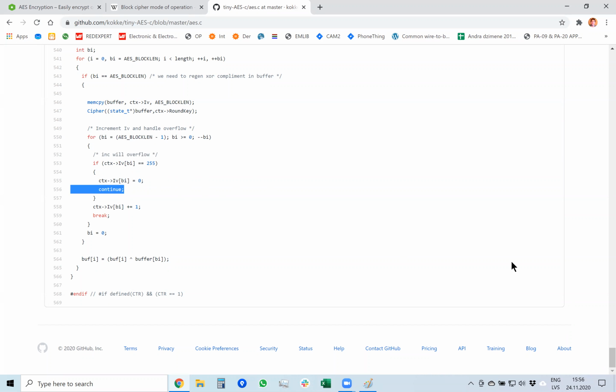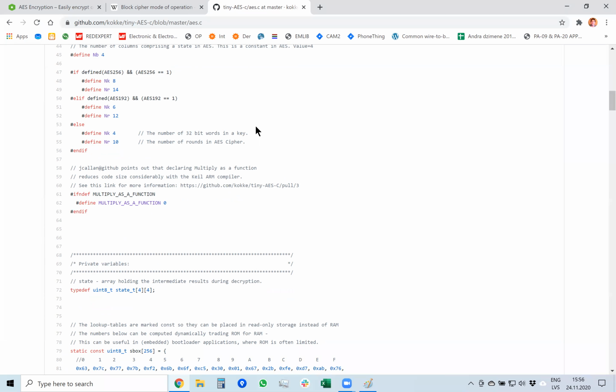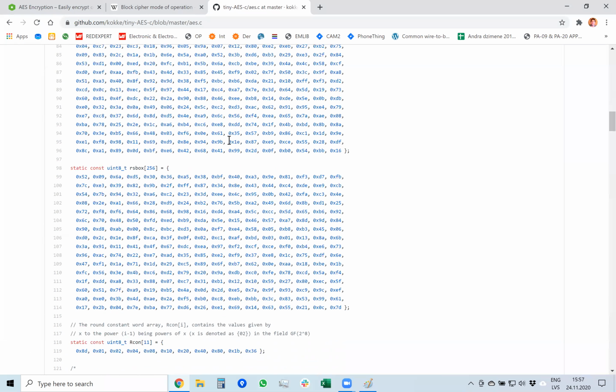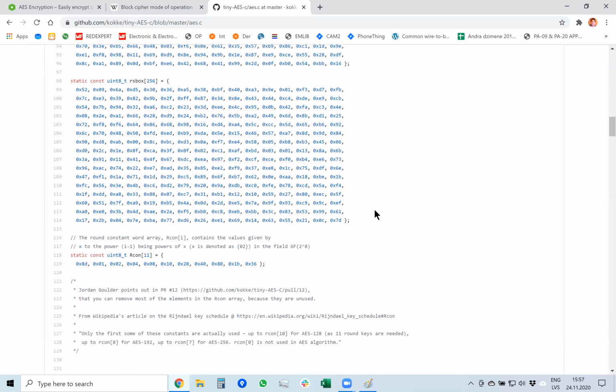But knowing that encryption is really important, people have started to build encryption, for example AES, as a hardware accelerated block inside the microcontrollers, because this can be easily done in hardware, since the process is really simple. Replacement can be done using a lookup table in read-only memory.